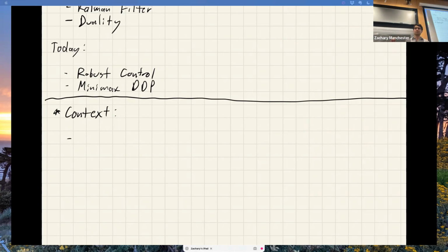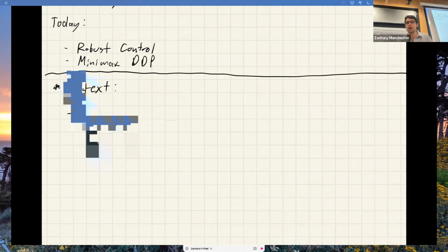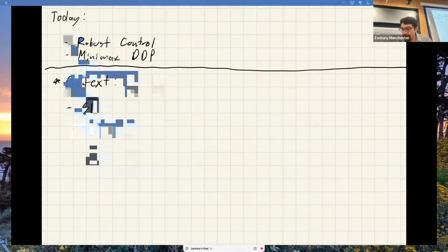If you have a constant bias in one of your model parameters and you do the standard LQG thing, thinking you'll just wrap this 10% uncertainty into your process noise, it absolutely doesn't look that way. You'll get stuff that drifts off and eventually blows up. So these are different things, and you can't typically think about these model errors as process noise. That's the main point there.